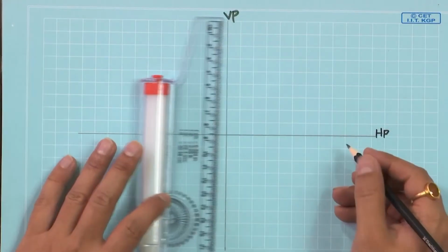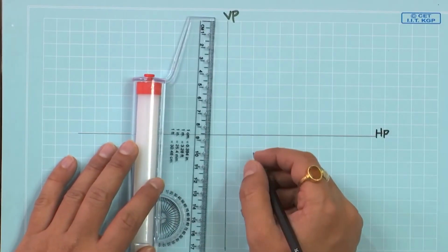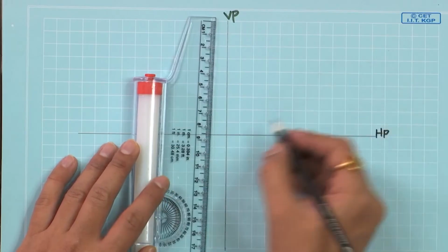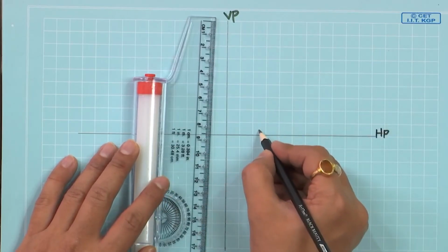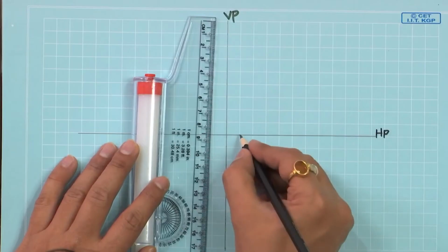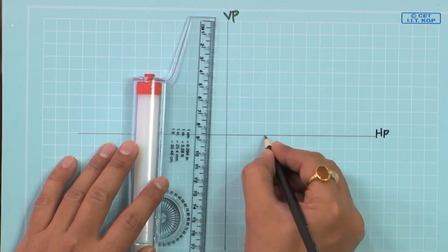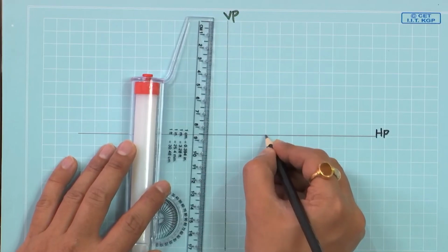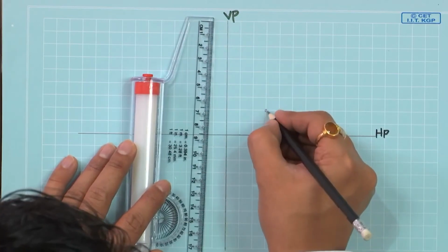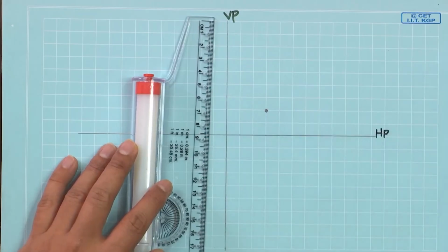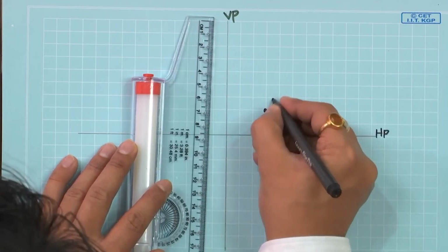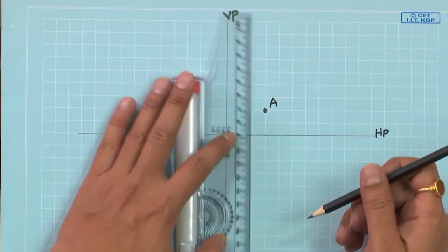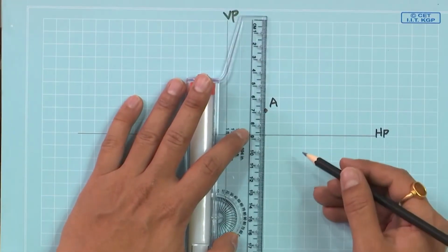We have to first project point A, somewhere A which is 30 units, 1, 2, 3 units. So, somewhere 10, 20, 30 here and 20 units above, that means 1, 2 units. So, this must be the point A, capital A, that we have to project onto this bottom.